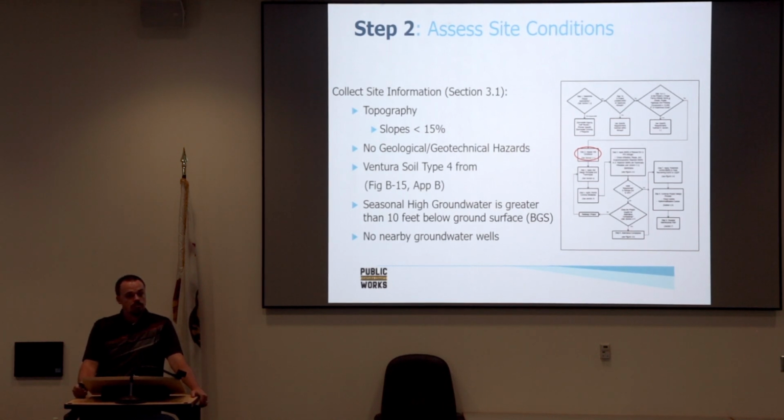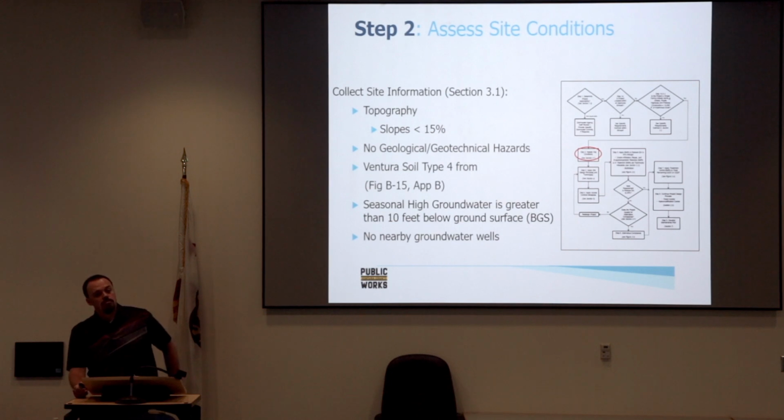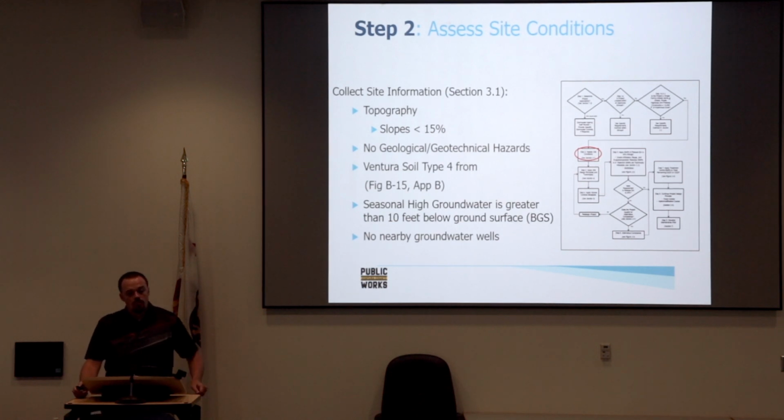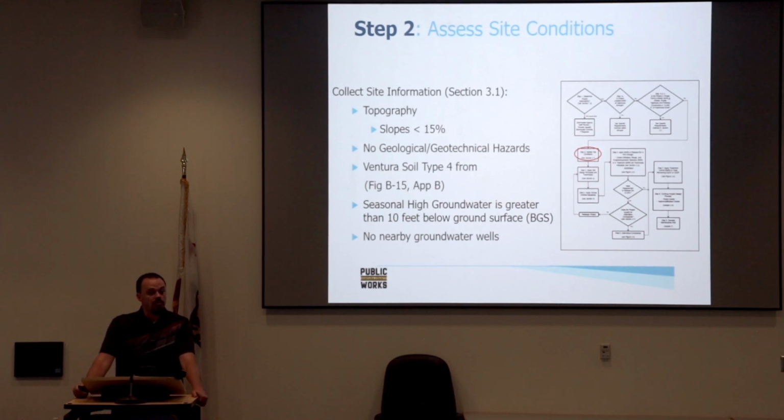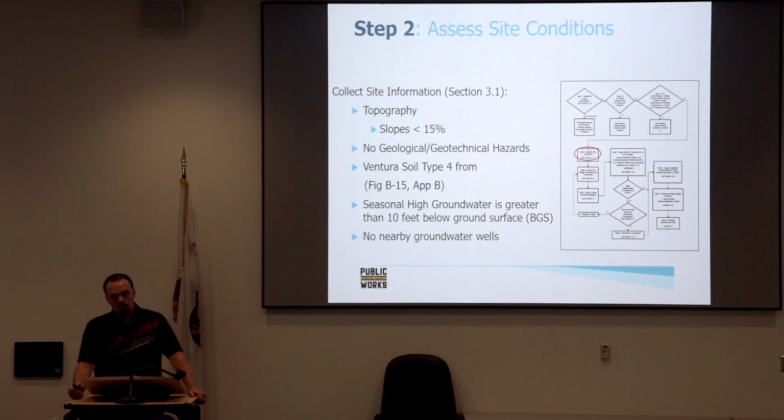And also, on the slope, 15% average, what areas are you calculating? Sorry, for the 15% slope? Yeah, is it for the developed portion or the undeveloped, the whole site? For this one, it was just identified as less than 15% because greater than 20% is the trigger for hillside or high-risk sites. So basically, that's just put in there to identify that this is not a high-risk site in this case. I'm just saying, how do you determine that trigger if you did have a site that was steep?